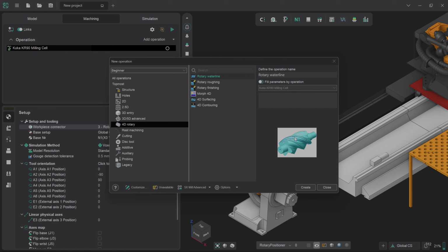So this will treat the radial axis in exactly the same way that a roughing waterline in a 3D space would do. So it will machine away the dominant chunk of the area, and then if you're using the cleanup cycle as well, it'll bring that into a much smaller, more refined cut. But obviously wrapped around the central axis instead of laid out flat across a panel. That's not an entirely appropriate toolpath for what we're working with at the moment, though. This is better suited to large-scale screw cutting, that kind of thing, and in the instance of this image, it's a large-scale Archimedean screw.